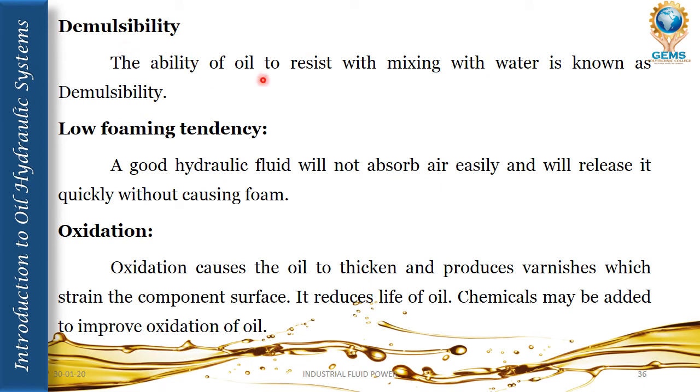Demulsibility. The ability of oil to resist mixing with water is known as demulsibility. Low foaming tendency. A good hydraulic fluid will not absorb air easily and will release it quickly without causing foam. Oxidation. Oxidation causes the oil to thicken and produces varnishes which stain the component surface. It reduces the life of the oil. Chemicals may be added to improve oxidation resistance of the oil.